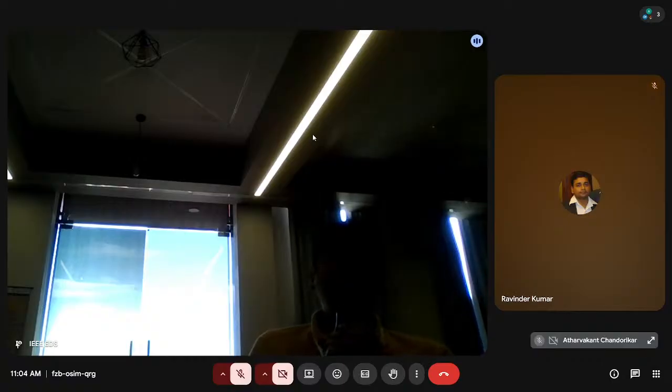Basically the germanium is substituting the tin sites and the tin is displaced, and by this ionization process it is releasing 2 electrons, and then these 2 electrons are reducing the tin 2+ to make the neutral tin atom, and you can see the evidence here. The tin atom is increasing from 7.60% to 25.19%. So there is a significant amount of tin atoms present in the germanium doped film.